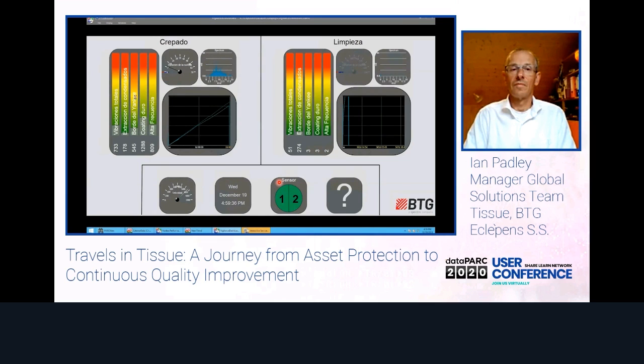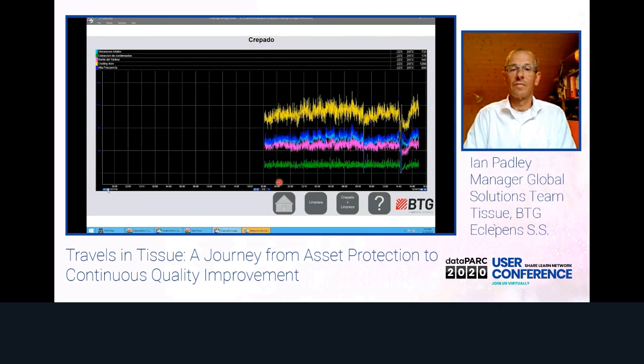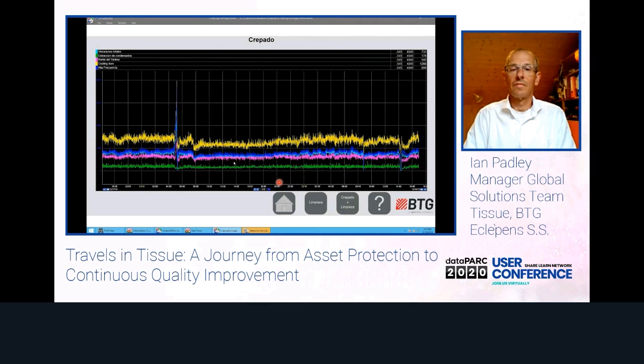To start, I click on the vibration levels. Now I can see the trends for the last 24 hours. Let's look back a little further. Something has caused the vibration to spike. Let's take a closer look.